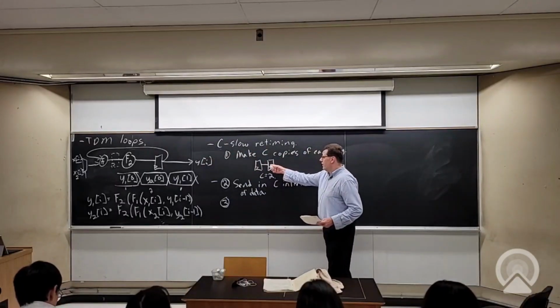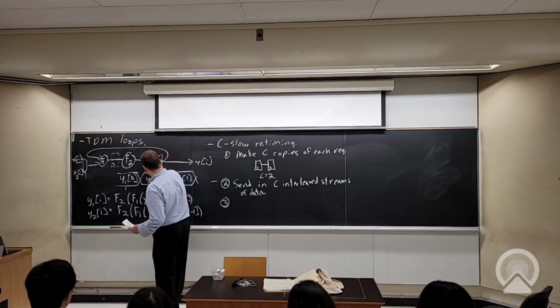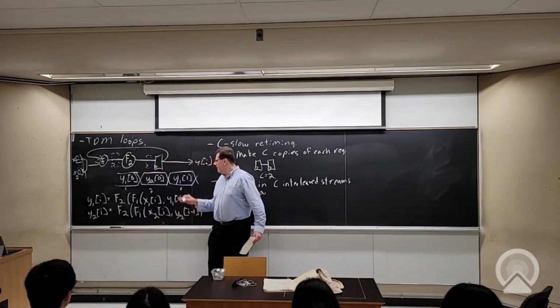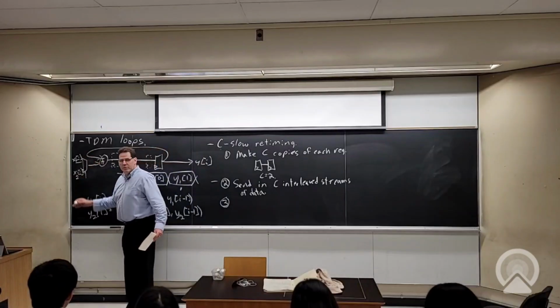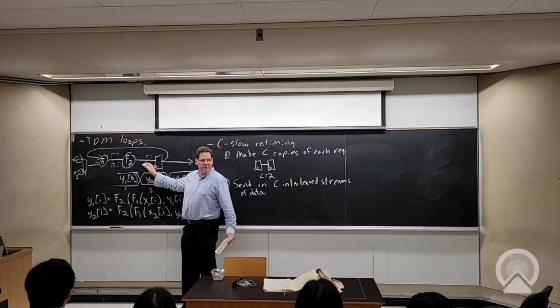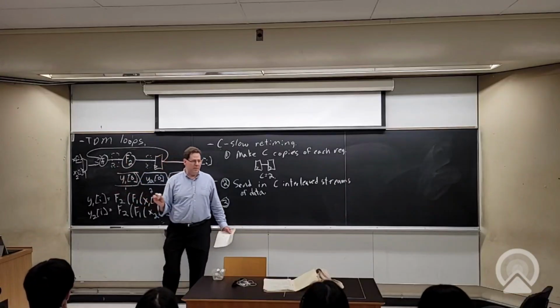If I did this optimization here, I would have put my second register right there, and then I time domain multiplex by a factor of 2, and it will work. But clearly, I didn't get a lot of frequency benefit from this. I just put 2 registers back to back, so my critical path is pretty much the same.